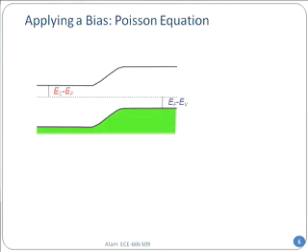Now this is the rule. You can see here that this is the band diagram in equilibrium. How do you know this is a band diagram in equilibrium? It is because the quasi-Fermi level, or Fermi level, E sub F, is flat throughout. And you know that when the quasi-Fermi level or Fermi level is flat throughout, there is no current flow in the system.